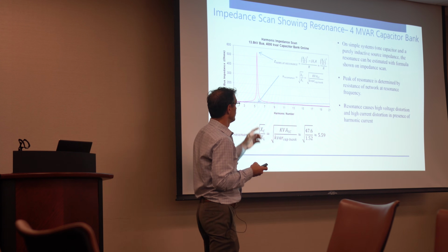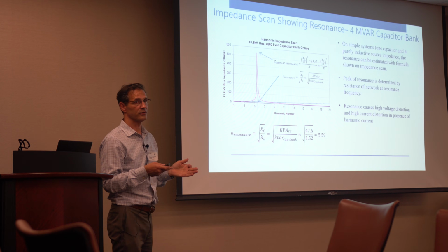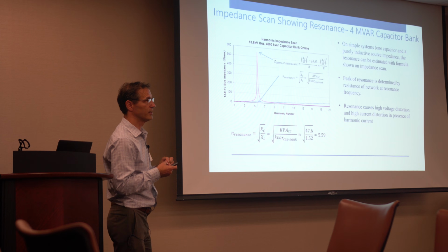So that's why I say you always have to be concerned about resonance, because if you have resonance when you add a capacitor bank, you got a potential for a big problem, even for very low-level harmonics.